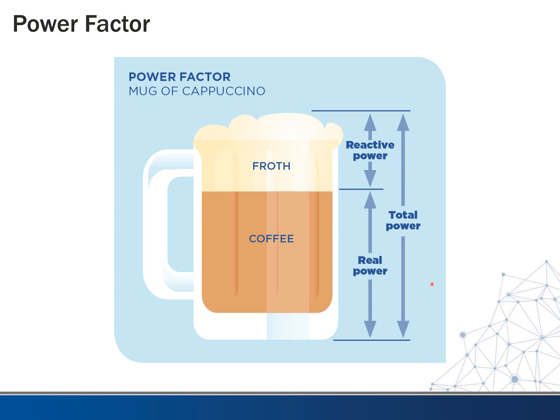The reason why this is an issue, and this is a graph people often use to talk about this, we define this total power as, again, when the current and the voltage are totally in phase. So this is the maximum we can get, right? As we start to go out of phase with a phase shift, remember our current and voltage aren't lined up together, so we start to see what's the real power. That's that smaller green line we saw in the second and third graph before. This is what we pay for, though, the total power. This is what we can actually utilize. As you can imagine, as this shrinks down more and more, we're paying for a lot more power than what we're using. So in an industrial application, this can be a problem. There's ways to correct that, which we may talk about in a later lecture, but basically by adding capacitance back in.